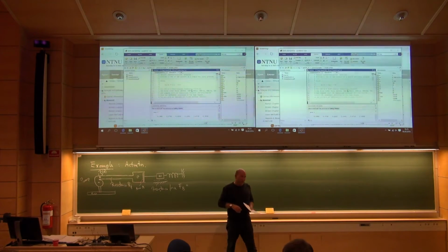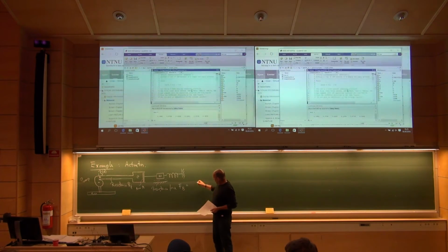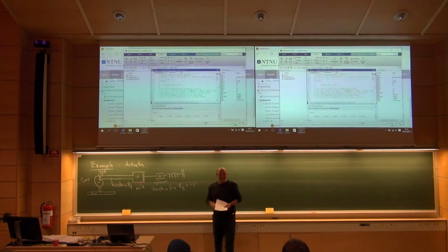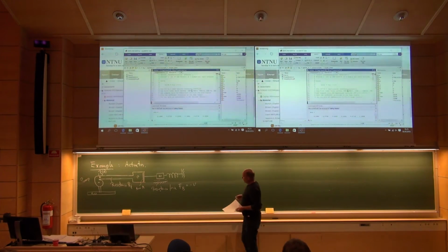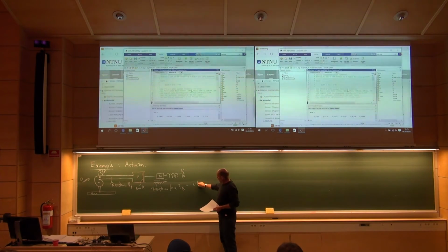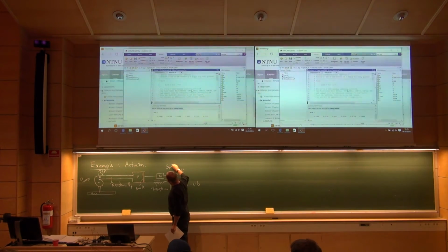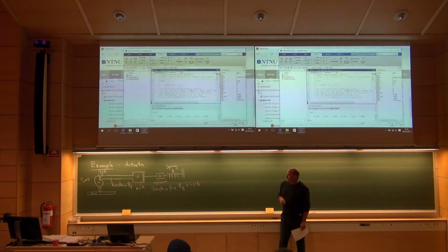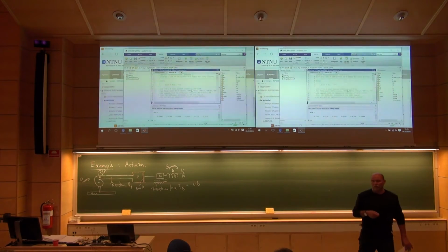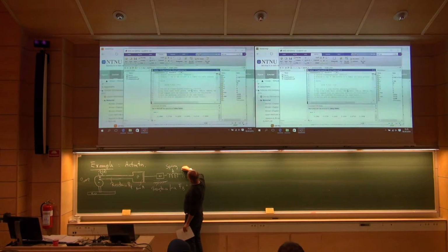And the model, a very simple model for a resistance force, sliding resistance, will be that the force is proportional to the velocity, but operates always in the negative velocity direction. So V, the velocity for the mass, negative, the force acts the other way. And then multiplied with a constant parameter B, something like that. The spring has a stiffness K. And before we begin to model and simulate this problem, we have to decide what the positive direction is. And here I choose positive direction to the west. So x.